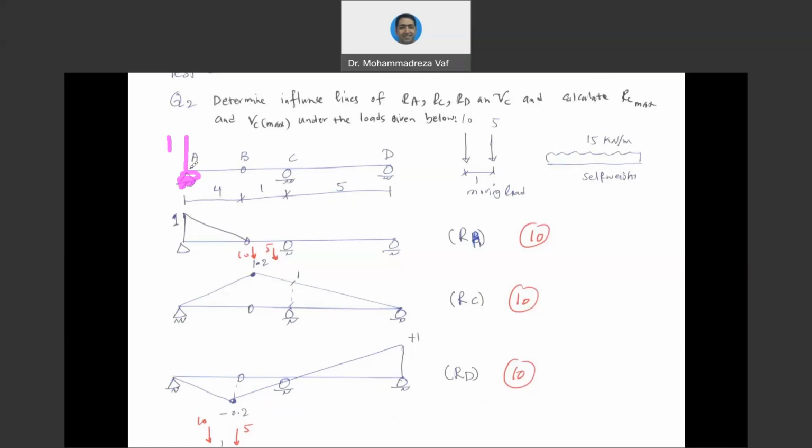So if we do that, you can see point A is going to move toward up, and then point B is connected to point A through an internal hinge. So if you have a hinge, you know that we can have easily a rotation in that location. Therefore, point B can rotate. However, for point B to be able to go up, we need to see whether point C allows it or not.